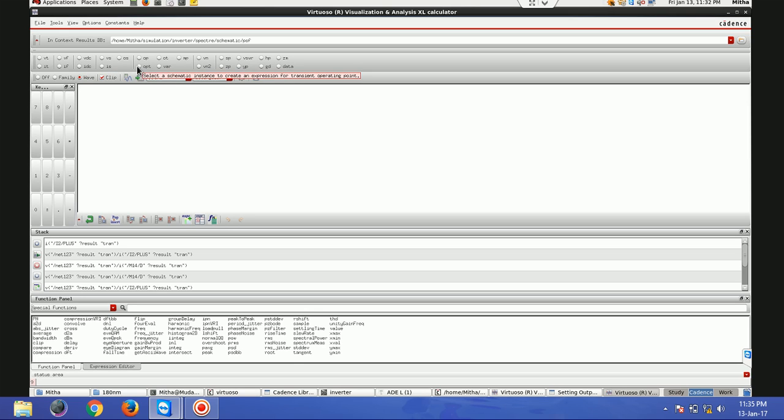And these are for operating conditions, like if I want to give some expression in which I define the VTH of my transistor, etc. And these are for RF design. So for now I'll show you some basic recordings for an inverter, mostly in transient simulation. What we see is rise time, fall time, delay, like that. And one more example I'll be showing when I take the AC response of some, I'll take one common source amplifier.